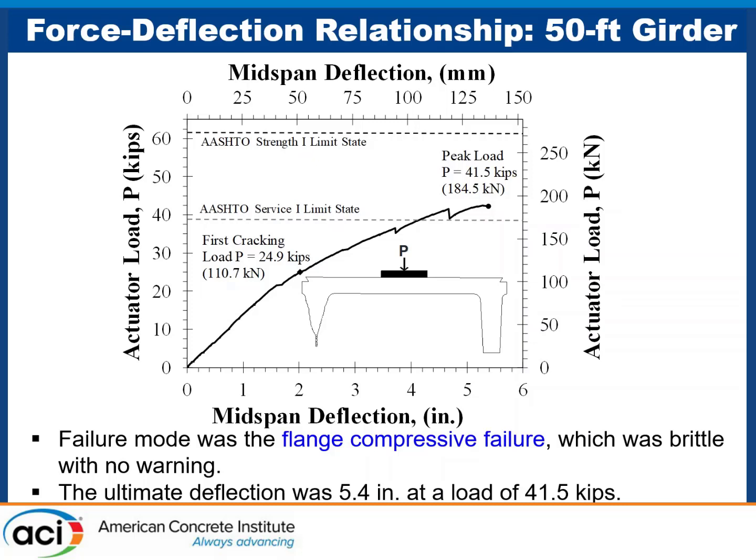It was not safe. So we used that data, and we wanted to say, if you see this damage, most of one of the legs of the concrete is gone, can you really predict this capacity? So that one was the goal. And we did a 40 feet length girder, healthy one, new one before this test. And to give you some perspective, it should have shown 10 inches of displacement while it failed at 5.5. So it was really a bad girder.